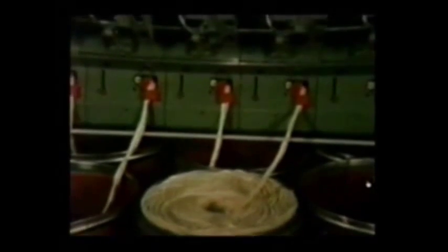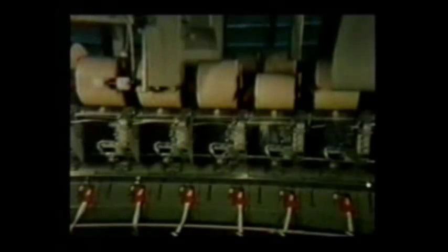This high-speed operation that dispenses the roving as well as the winding is also associated with a great deal of automation. The carriage that you see going around the frame, patrolling every rotor head, indeed acts as a piecer. It pieces the yarn if it breaks. It also cleans up the rotor box in case of trash accumulation, and in addition to all of that, it also does the packages.